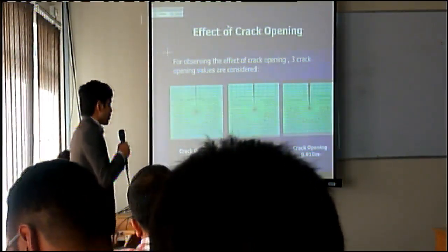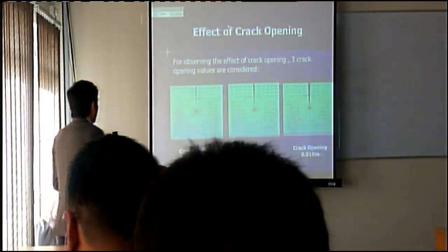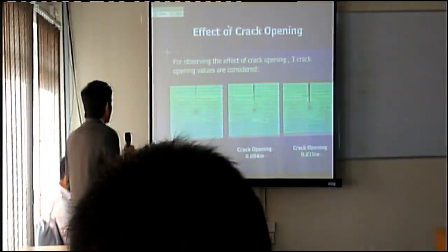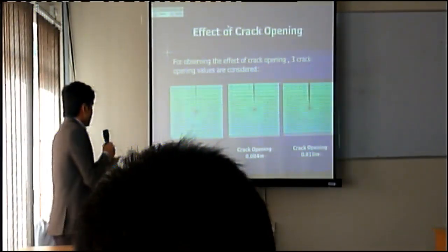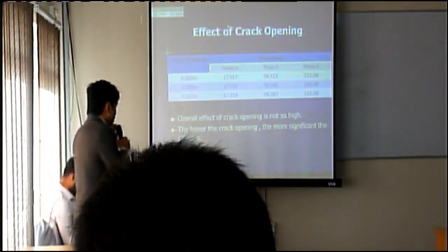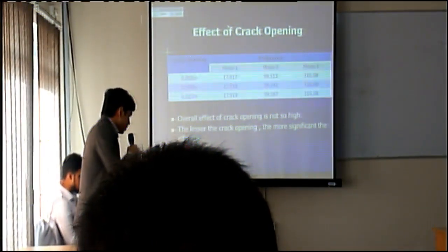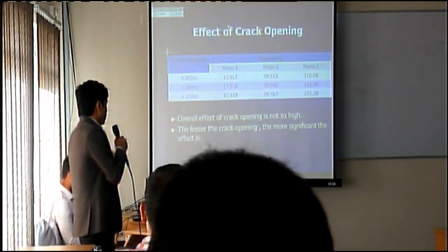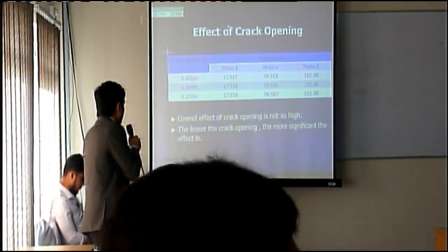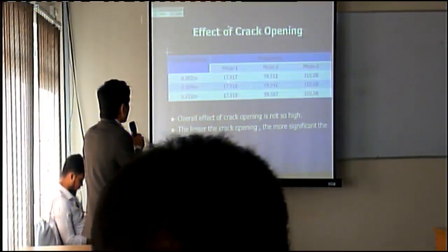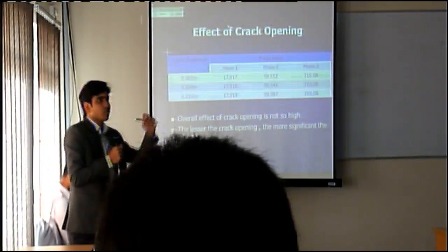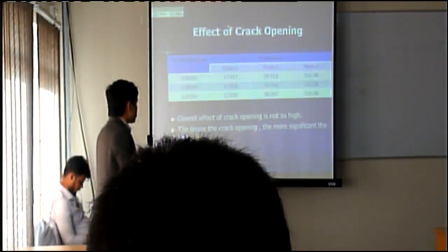Now the effect of crack opening. The crack opening size is 10 millimeter, 4 millimeter and 2 millimeter. As the crack opening reduces, that is the crack opening size is lesser, the frequency variation is also significant, but the result is, you see there, the result is somewhat similar and varies in the second or third digit,